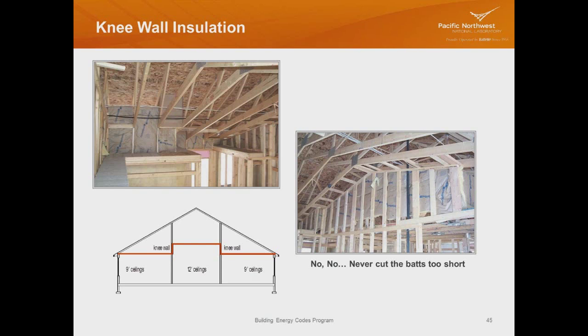It makes assumptions if you're using typical standard flat ceiling scissor truss that there is decreased amount of insulation towards the eaves. It's running that calculation as well. And only if it's an energy truss do you get full height, full credit for that entire R value for that ceiling insulation. So don't double up your R values for your ceiling. Enter it as cavity unless you're insulating truly with foam board at the roof deck outside of the structural members would you show continuous insulation for your ceiling or your roof entry.